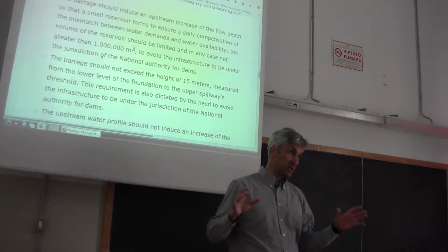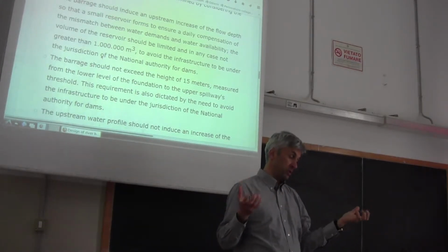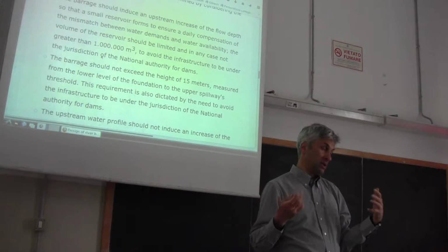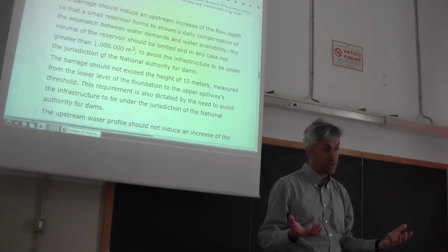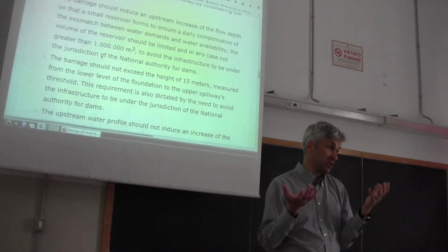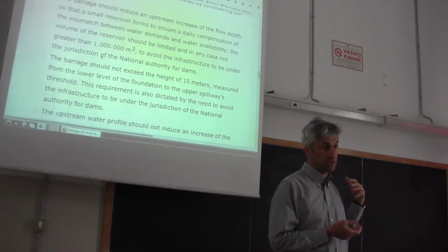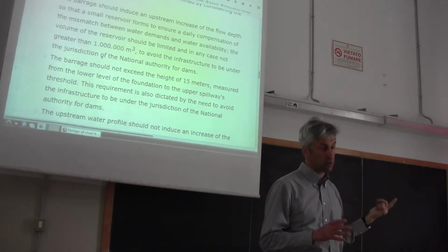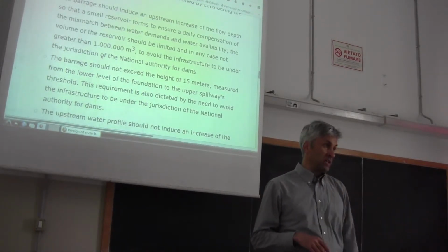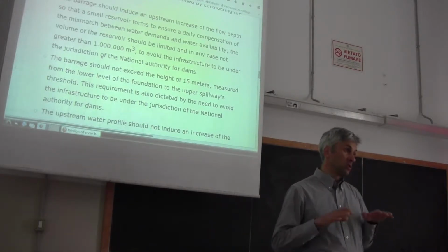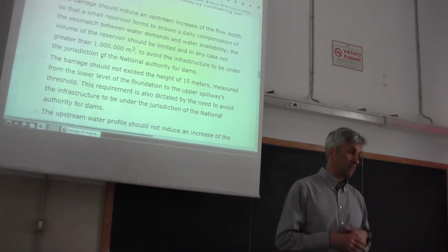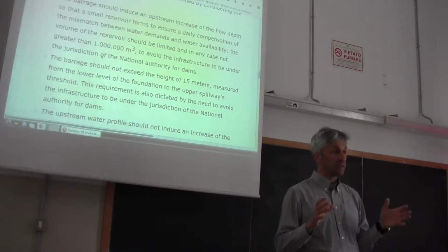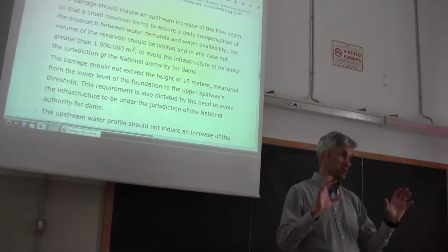And once that you determined, you collected all the required information, of course, you evaluate alternative solutions. Usually we try to keep it at the highest elevation as possible, because we want to use the upstream reservoir. On the other hand, we don't want to increase the flood risk, we don't want to create instability on the hill slopes, and we don't want to go under the competence of the National Authority for Dams. I cannot give a precise law, a deterministic relationship for determining the overall elevation of the structure.